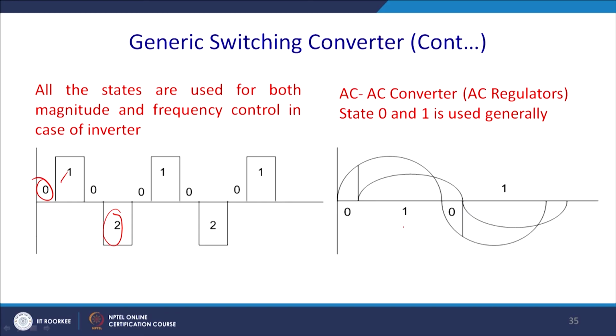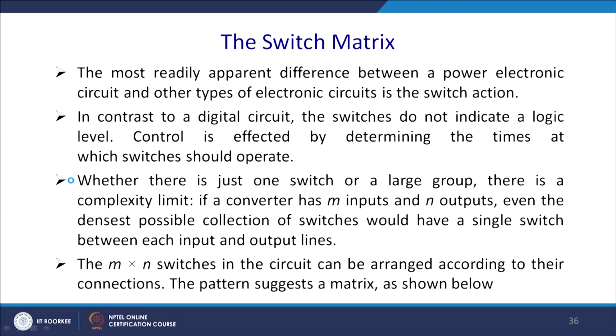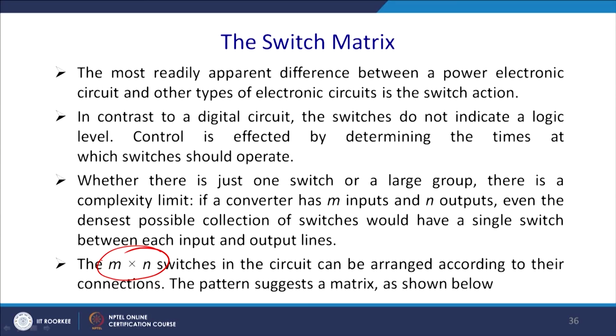Accordingly, you can choose different kinds of states and different voltages can be generated. So, this is direct AC to AC conversion. Now, this is a matrix converter. What does a matrix converter do? We have to realize the switching matrix so that it gives you direct AC to AC conversion. Otherwise, it is possible to convert AC to DC, and thereafter DC to AC. If you wish to have a direct conversion, there is a different way. So, AC to AC, variable AC to fixed AC and vice versa, we require something called a matrix converter. We shall discuss later how it has been realized and practiced.